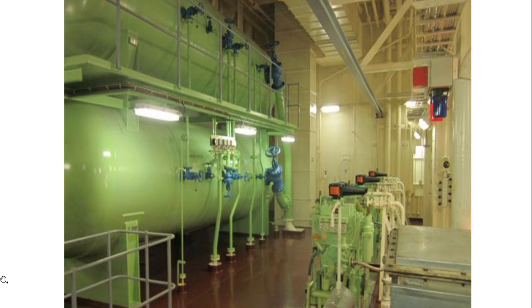So today we saw the different types of compressors, which type of compressor is broadly used on ships, and what the SOLAS requirement for air compressors is, as per quantity and filling capacity. Then we saw free air delivery, what it is, what the safety devices on an air compressor are, and then we saw the main air reservoir, its different positions, the SOLAS requirements, the safety devices fitted on the main reservoir, why there is a compensation ring, and why the manhole door is elliptical in shape. Now all those things we covered, and also the function of a fusible plug and its fusing temperature, all in detail. Thank you so much.